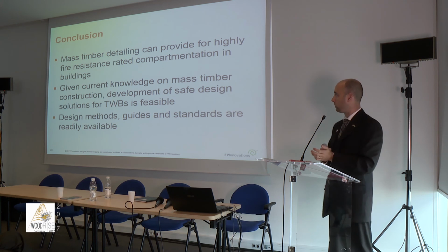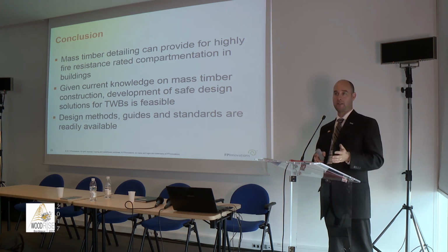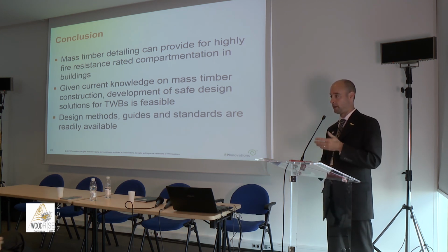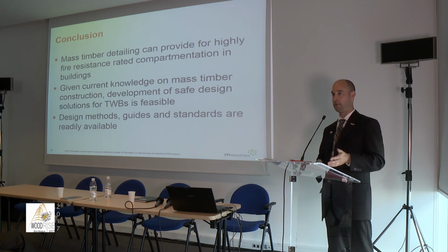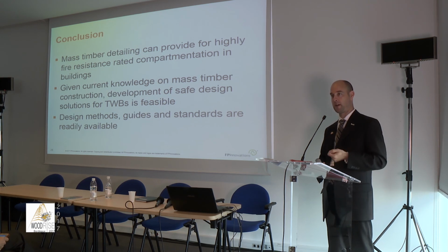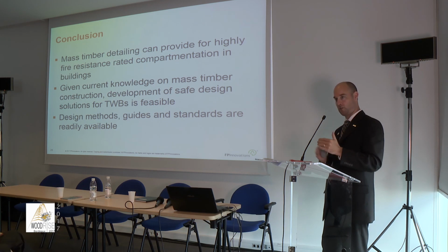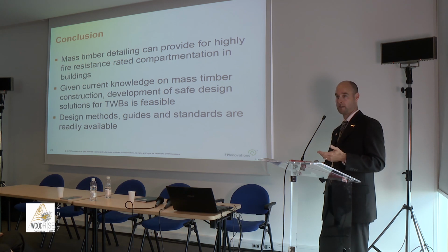So in conclusion, there's a lot of testing that has been done out there. Calculation methods exist for a number of years already. Eurocode 5 is really well detailed. There's many other standards, Japan, Canada, US, that provide how to calculate fire resistance, but they sometimes have limitations on the duration. However, tests show that beyond 2 hours, it can easily be achieved by mass timber elements. So it's really not an issue.